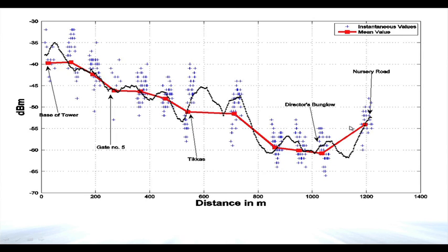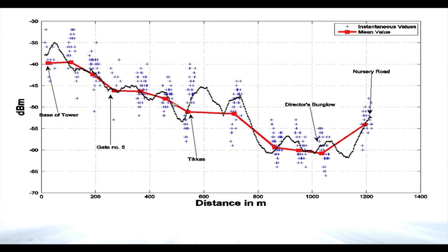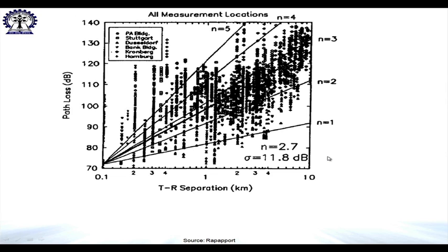If it was only path loss in nature, we would have expected a straight line in this direction with a particular slope. However, what we have received is fluctuations, where signal strength goes down and then again goes up, it could again go down, but on an average there is a decrease across distance. But to cater to these local fluctuations, as we are seeing, we need to improve upon the model which we have discussed till now. Now, this result is again from Rappaport.